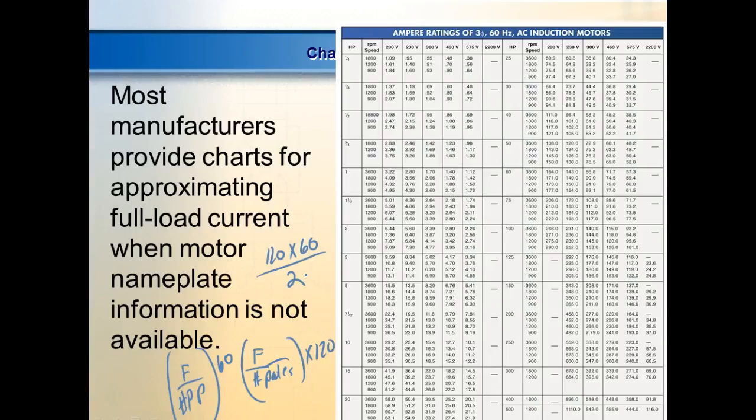Well, this is what they do. So this is one way that they change the speed of a motor. If you got a ceiling fan in your house, you flip that switch, you're changing the number of poles. If you look, it's got 3 wires coming out, and that's all it's doing. It's shifting either more or less poles. This is a 3-speed motor.